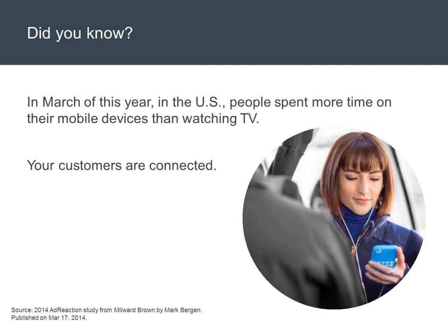So with all three of those, all the products have to speak that same language. They can all be talking to each other wirelessly. In terms of comparison, Zigbee seems to be reasonably popular with accessories, commercially speaking, on niche products. Redlink is a Honeywell thing, although they use it in their thermostats and in some of their security products. But you can't mix and match any of those things. Redlink can't be mixed with Zigbee and vice versa. But they're all local area protocols to get things talking to each other. And then at some point, those things have to connect to something else to get on the internet. Like in the case of Redlink, we got that little black router that gets all the Redlink in the entire building onto the internet. So hopefully that helps with that. I'll give it back to Greg here. Thanks, Ryan.